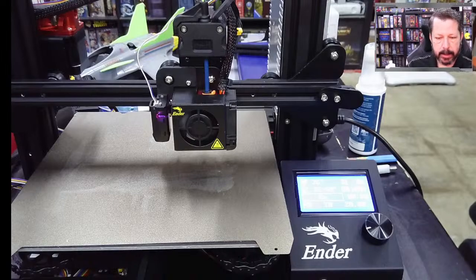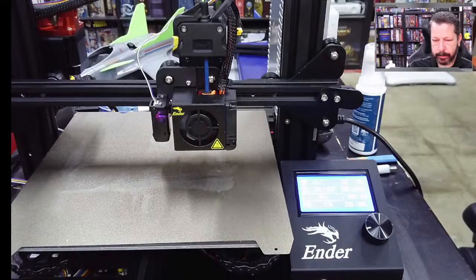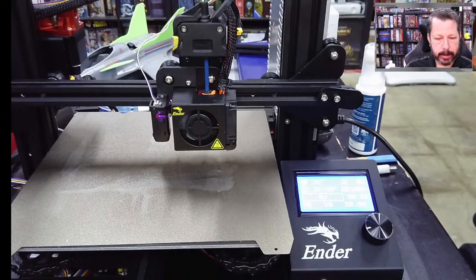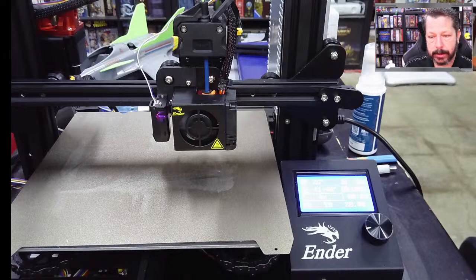So the other thing you could do is Cura. You can just put a retraction test in here. There's the model that we had before. This little guy. Let's get him off of there. You can just add in a retraction test here. The difference here, now this is a much shorter test, but here you will just get one set of settings. So you can go into your settings and look for retract.